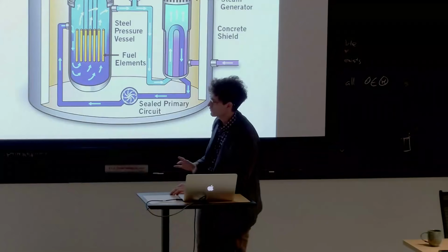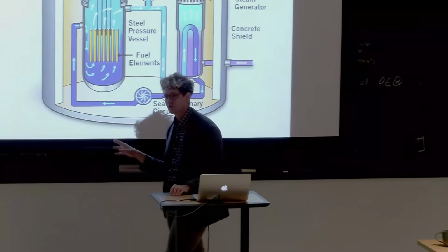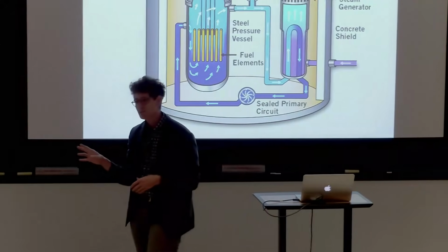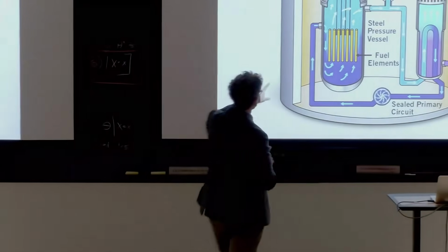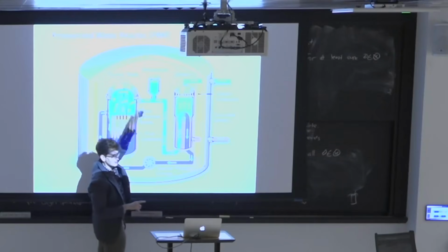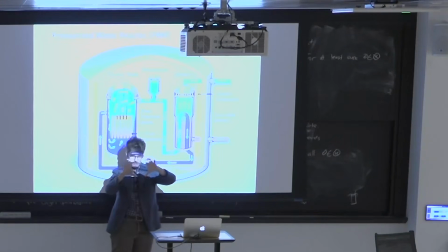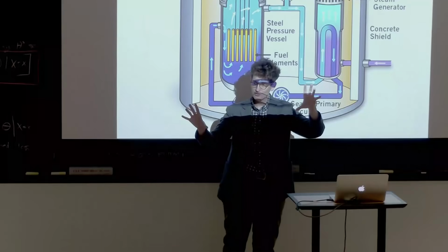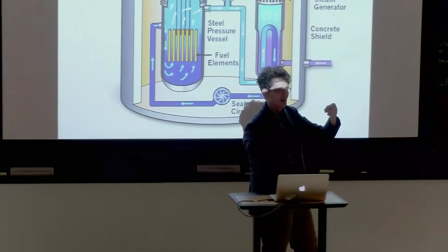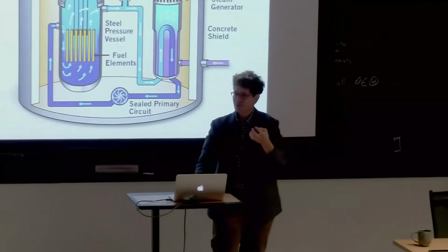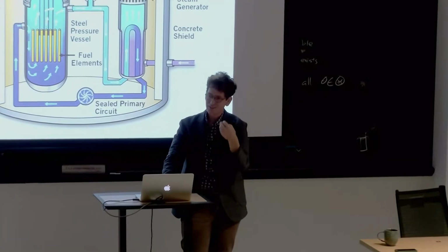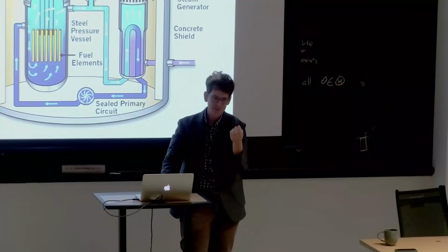So some of the pressurized water reactors that are currently being stood up in France, was called the EPR, and the top cap of, actually, I can't remember if it was the top cap or the bottom cap. One of the caps, really thick steel casting to hold all the pressure in, but it turned out when they cast it, there were some precipitates of carbon in the steel, which weakens the steel, which means that now they're not sure if that thing will last very long.